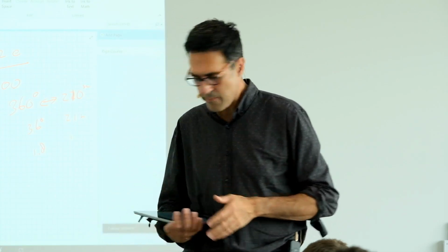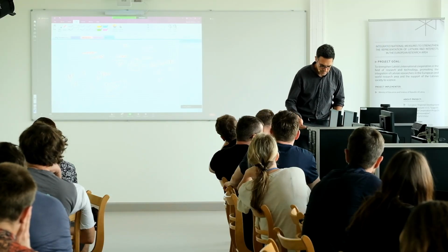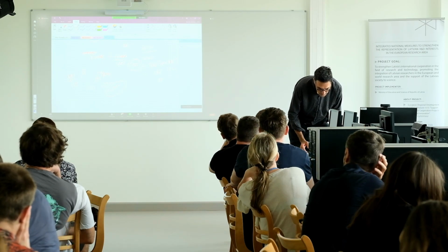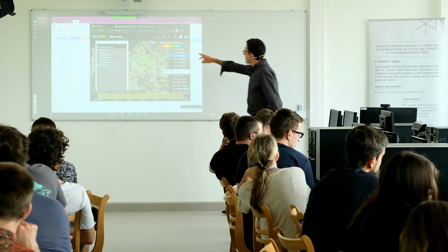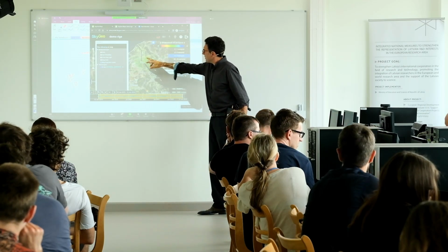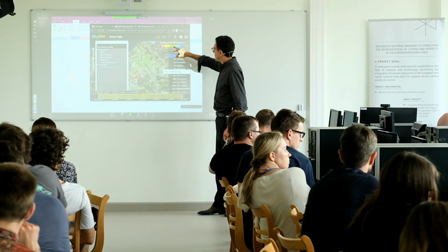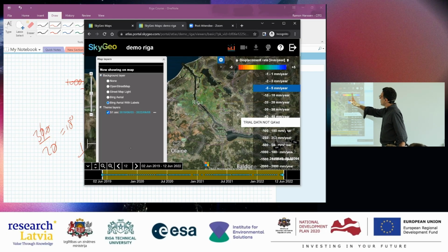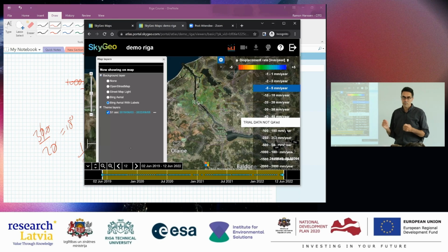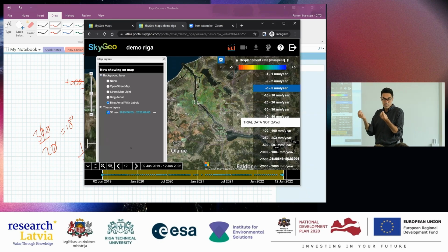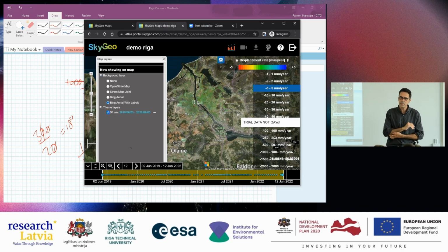So basically, on the map, what you see is displacement rate in millimeter per year. Now there is more greenish, you can zoom in later by yourself, but we don't know perfectly where 0 millimeter per year is. What we do know is the relative motion. So if a point is red and the next point is green, then the difference between these two is very accurate. But we cannot really say without any calibration where 0 millimeter per year is. Yeah?